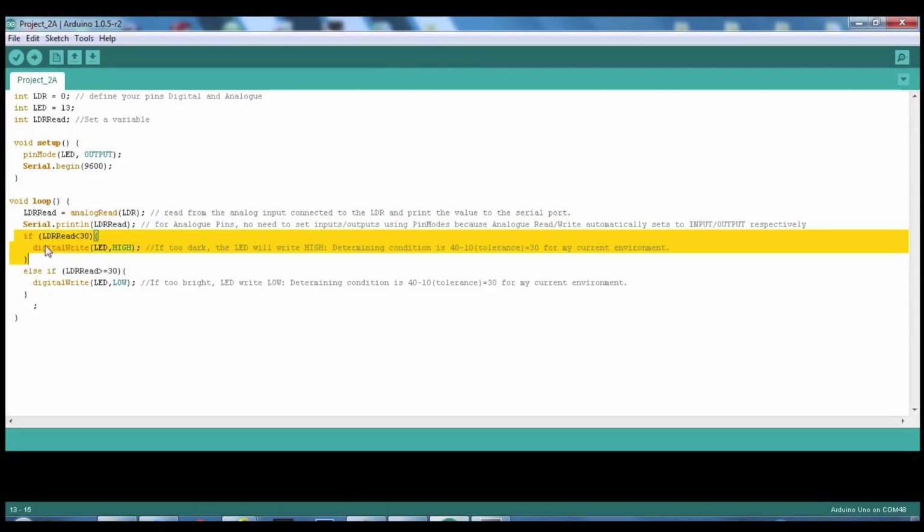6. If. For our case, our threshold condition in the lab is 30. If I switch on my lights, the number rises way above 30. If I switch them off, it goes below 30. It is safer to consider certain tolerance towards choosing the threshold condition to ensure a more robust system.